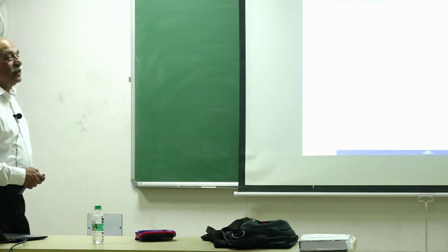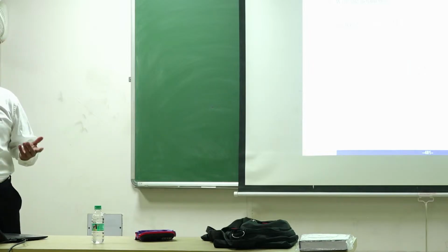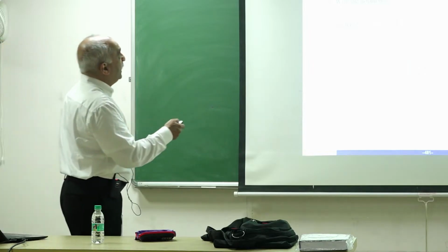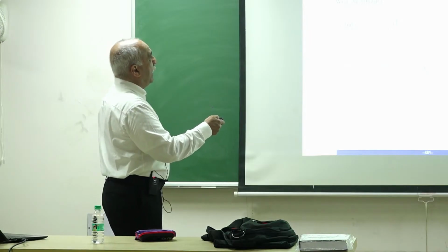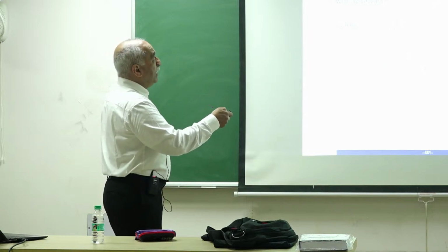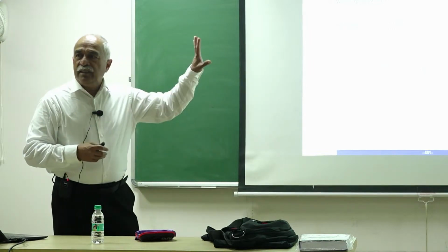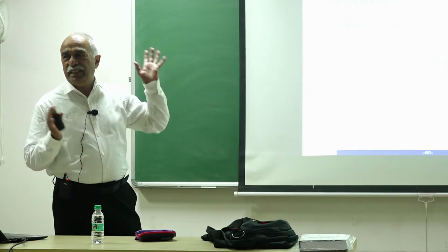So now let's look at the DFT, which you're all familiar with. For the DFT, L is defined as L_kn equal to exponential minus j2 pi over N, where capital N is the number of samples, times kn. n is the time index, k is the frequency index. That's the DFT kernel function, basis function.